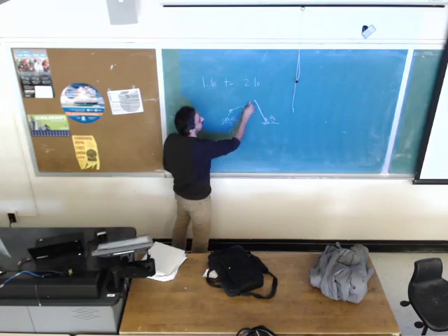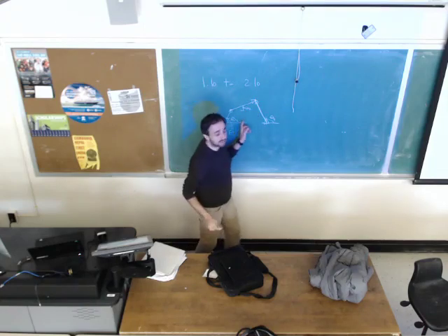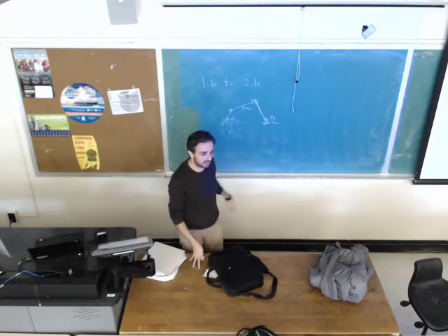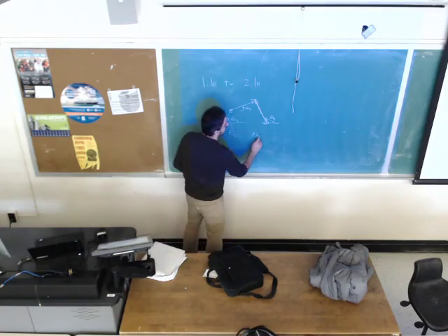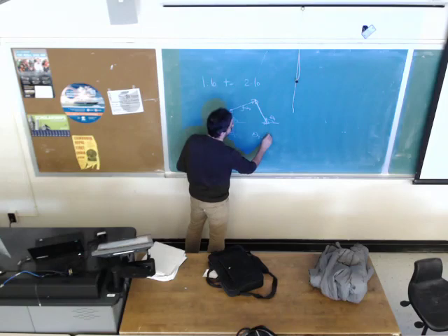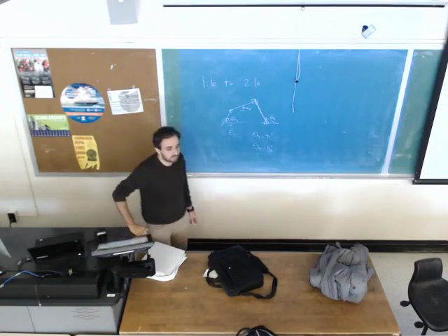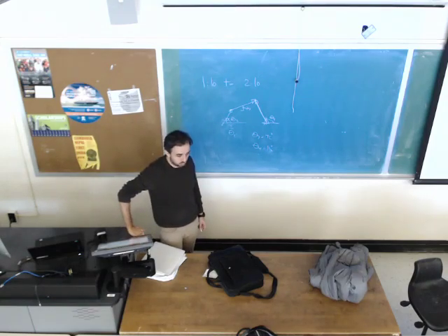To do that, you have to write the displacement equation and differentiate to get the velocity equation. But if I give you theta 3 equals, for example, 42 degrees, theta 4 is 110, then when it comes to getting a value for the velocity or acceleration, you should be able to solve it. I may ask you to calculate.